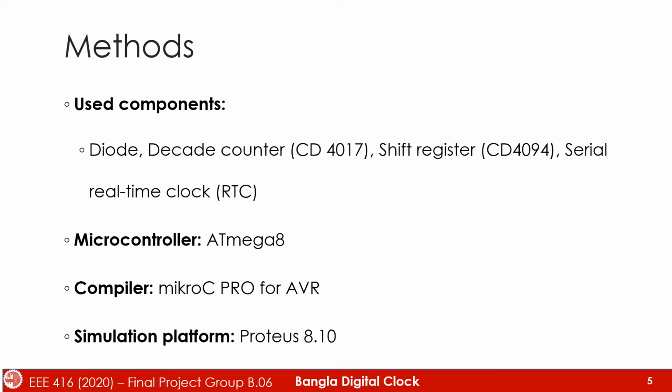For this project, we used diodes, a decade counter for counting in decimal digits, 4 shift registers for storage and movement of data, and a serial real-time clock. The project was constructed using the ATMEGA8, a low-power CMOS 8-bit microcontroller, and it was simulated in the platform Proteus 8.0.